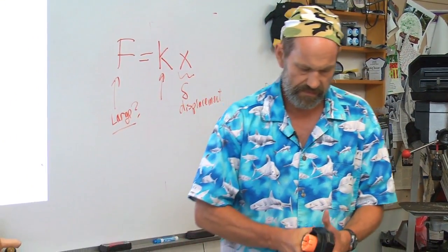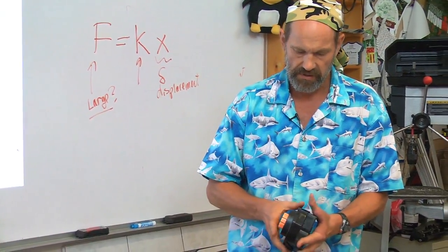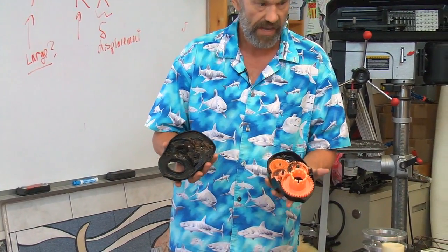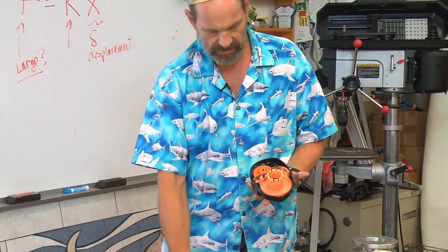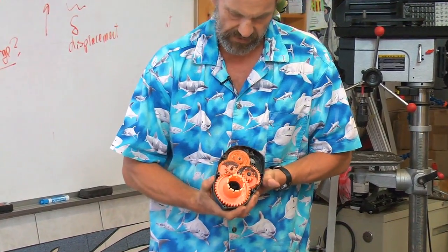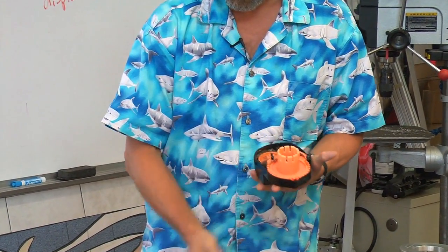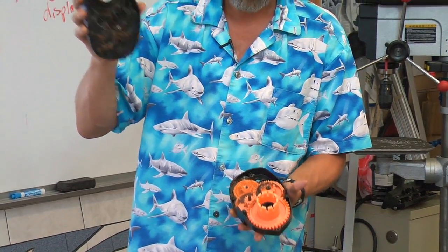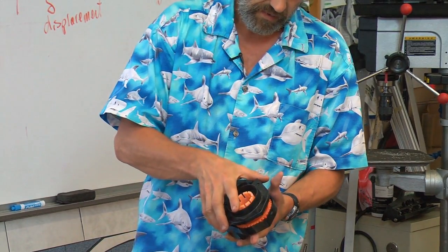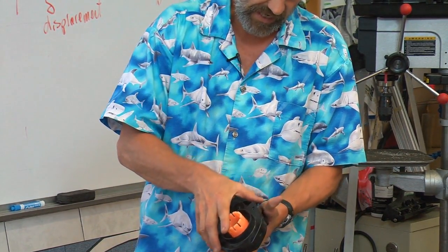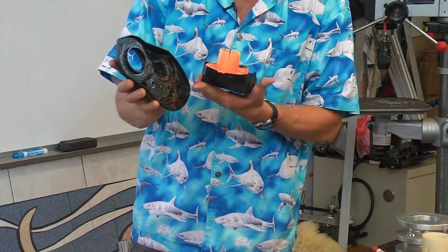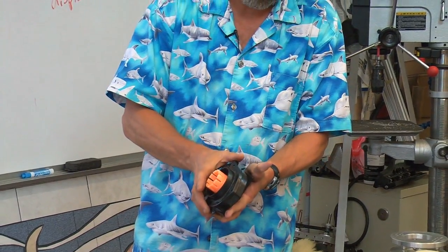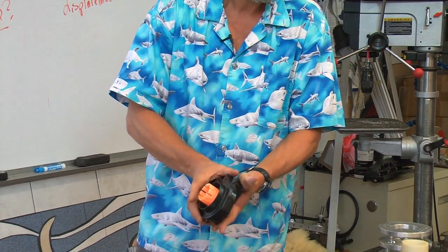So for example, we showed last time when we were talking about gears, this modular transmission, and how the housing itself with these finite thin thickness walls, which, you see, are a little soft, and the shaft features for the gears, and then the mating features on this part, I bring them together, and they don't exactly fit. They fit pretty close. There's some lead-in tapers, so it gets things reasonably closely aligned, and then when you push on them, it snaps together.